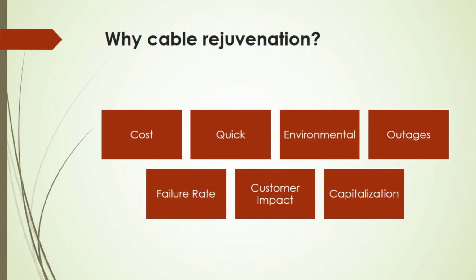There are 7 reasons to adopt cable rejuvenation. The primary motivation for circuit owners to employ cable rejuvenation nowadays is to save money. In most cases, the cost of rejuvenation is half to 1/3 of the cost of cable replacement. If the region is heavily manicured, difficult to reach, or the soil is actually rocky, the cost reductions can be much larger. The circuit owner may stretch their capital budget 2 or more times with cable rejuvenation and have a greater influence on their grid's dependability.